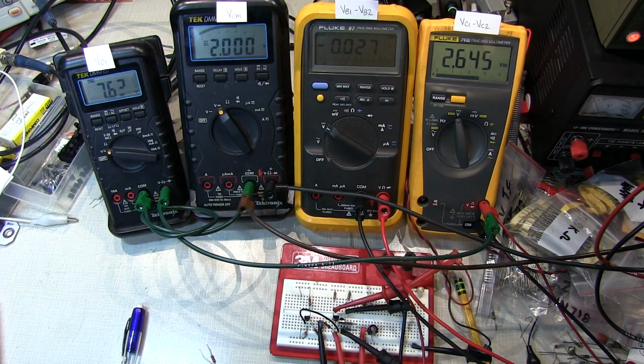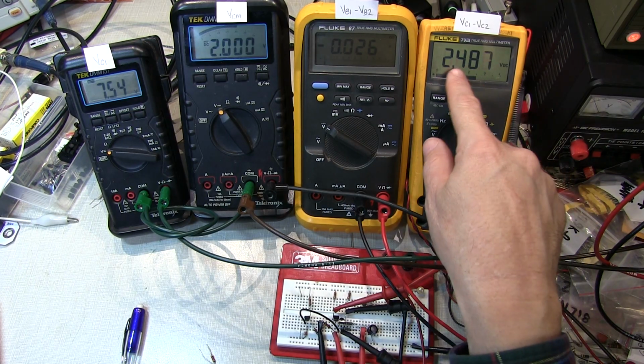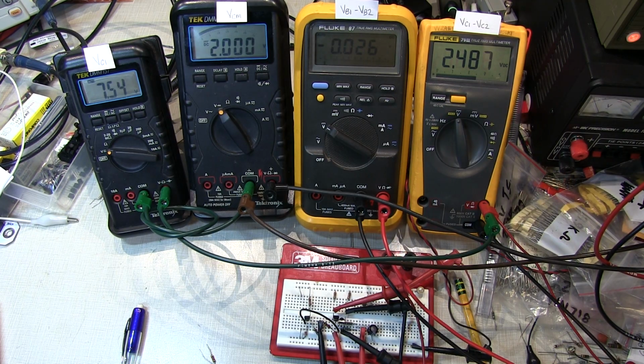Okay, so I've moved the common mode voltage down to 2 volts, and I'm just dialing in that minus 25 millivolt input difference here, and let's see if I can get close in there, right about there. So I can see that even with a 1 volt change in the common mode, I'm pretty close to that minus 26 millivolt input difference, and I'm sitting at that 2.48 output voltage difference. You know, a slight change, but not nearly as much as we saw with the tail resistor as opposed to a current source for that tail current.